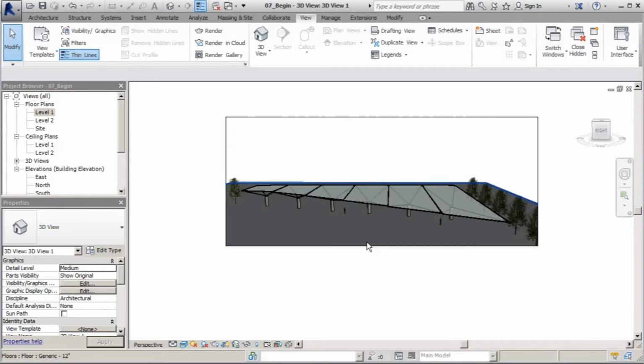We took it a little bit further and kicked it up a notch and went into a family environment and created our own pattern. And we used a little trick for using that pattern to host the structure for this system. That way we saved a ton of time and headache on not having to create different struts and elements within that structural system. And then once we were able to do that, we were able to tweak our design and our form just a little bit. We brought it into this project environment to really finish it off.